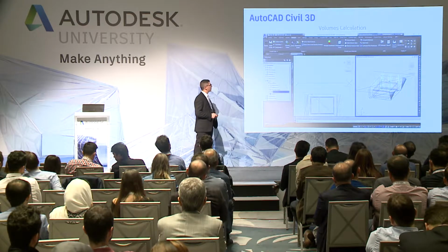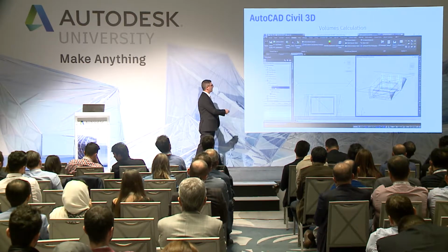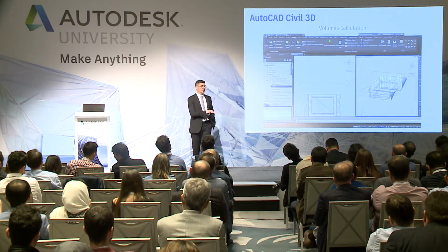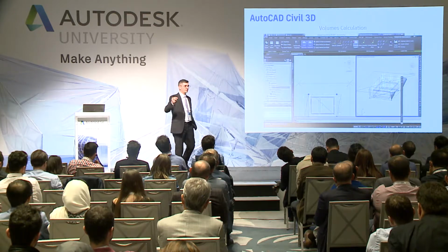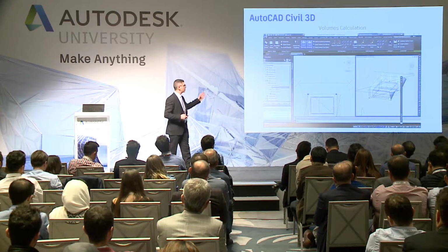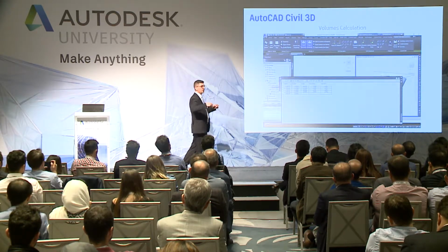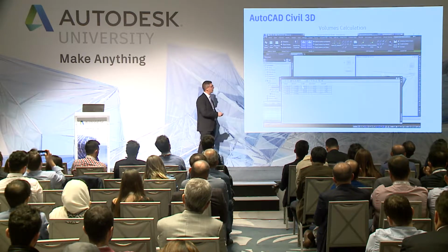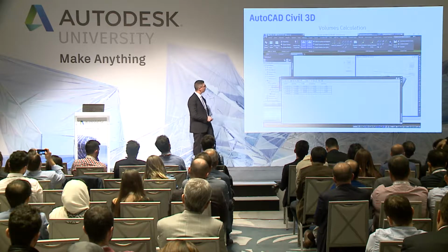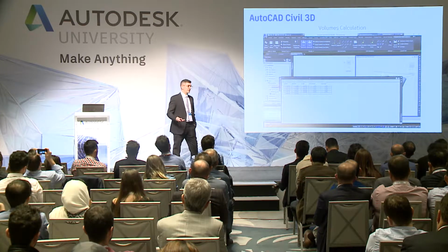And then I have the possibility to also change the elevation of the base of my foundation. Maybe you change something in your Revit model, OK? You can change the shape, you can change the structure, but maybe you need to change the elevation. If I change the elevation, the model is already updated because it's dynamic.